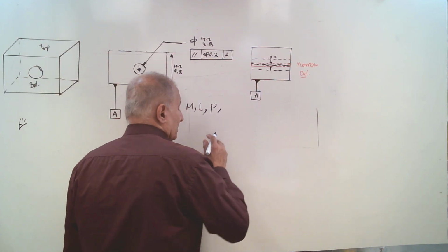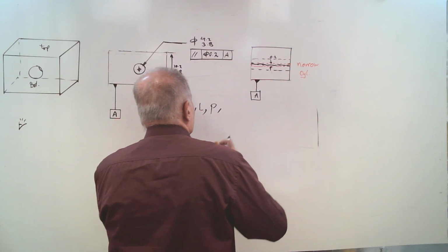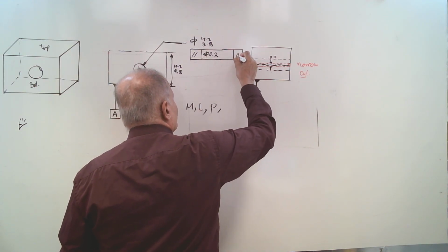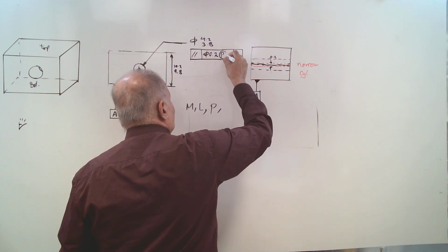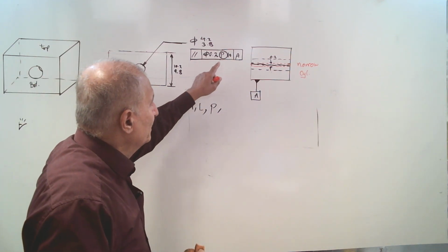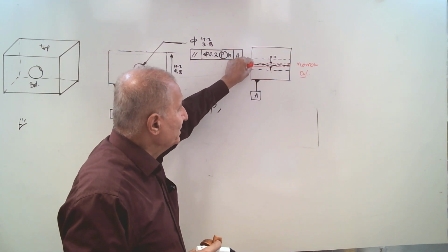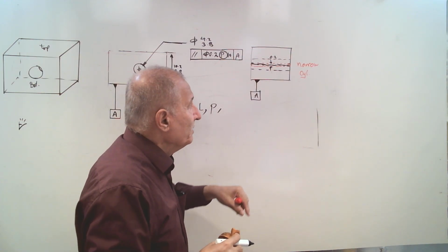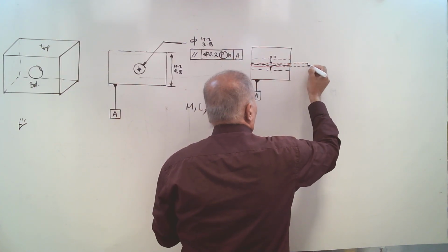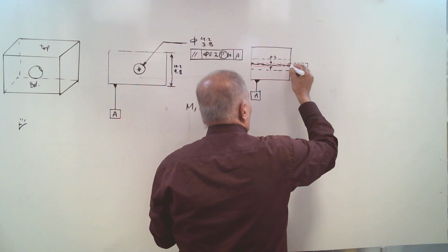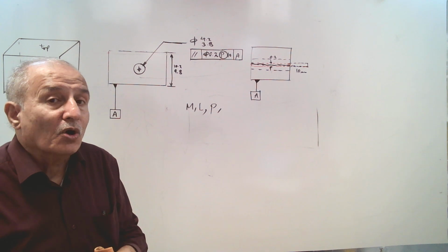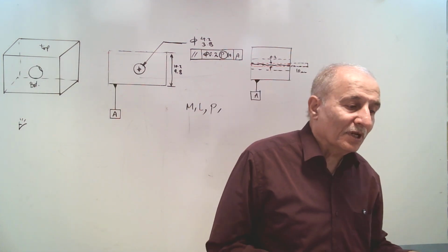If I put the P modifier here, 10, it means that the axis of this hole not only must be within this narrow cylinder, but if we extend this narrow cylinder outside, how much? 10 millimeter, and I extend the axis, it must still be inside this zone because this is required for assembly.